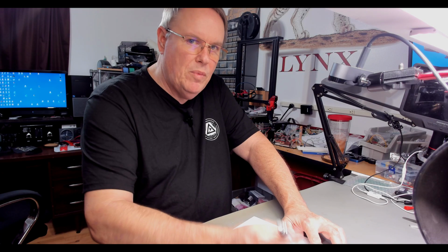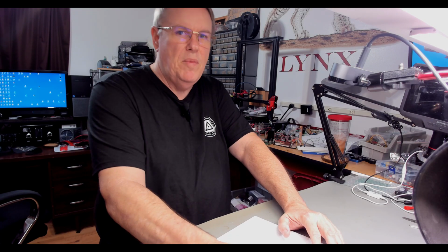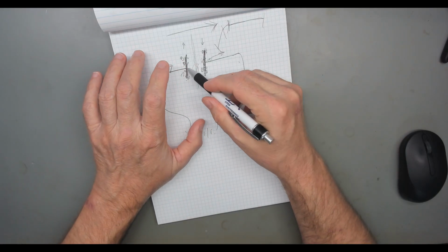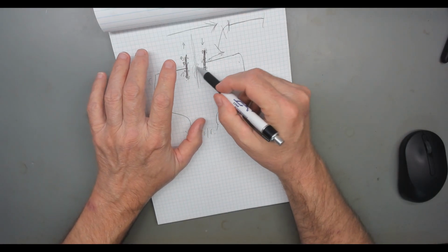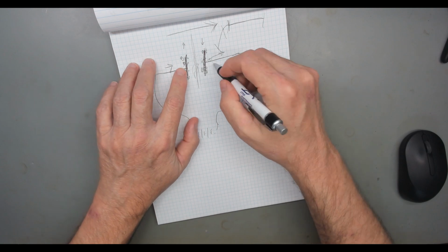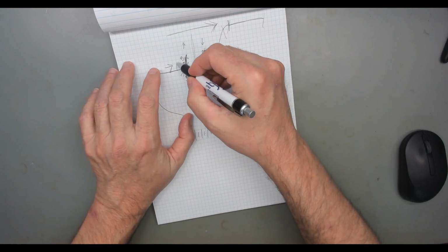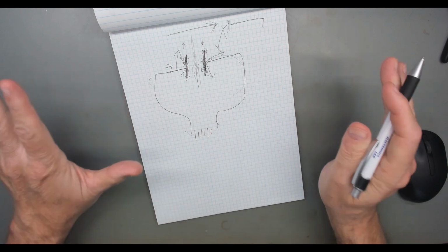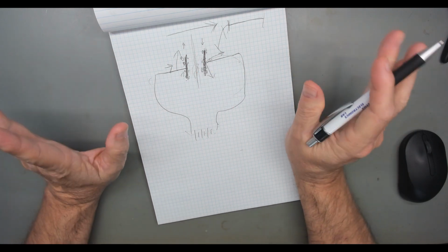They didn't flow through it before. I want to be clear on that. There are going to be people that argue, and you can put it in my comments and go on, but no current flowed other than leakage current. No normal current flowed here. It just reduced electrons here, increased electrons here, moved them through the circuit. By all measurements, you will see current. It'll look like it's flowing through the capacitor, but it's not.